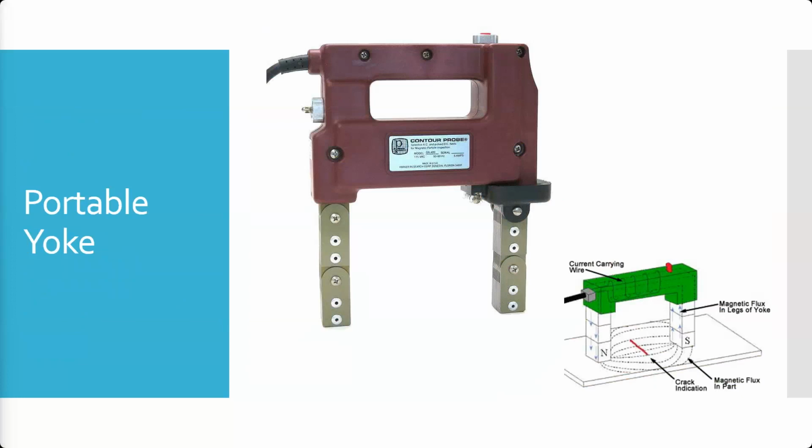These also, we had another use for these. We talked about how we have to demagnetize parts when we're done. And we demagnetize parts by putting them in a collapsing field. We'll look at how that works in a minute. We would often use these to demagnetize parts on the airplane after something like a lightning strike. So when lightning hits an airplane, travels through, that's a strong current that runs through the aircraft. And steel parts on the aircraft, when that current runs through them, can become magnetized. The ones that were particularly prone to that were the landing gear legs, the steel components on the landing gear.